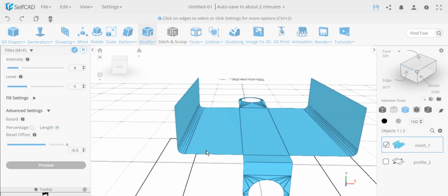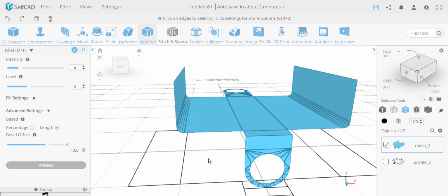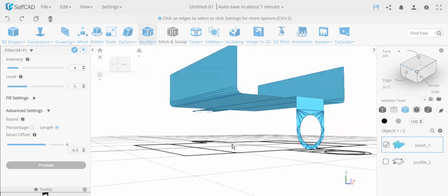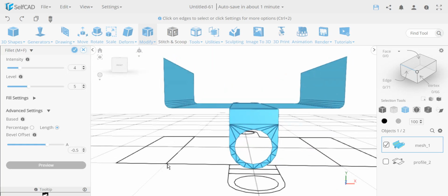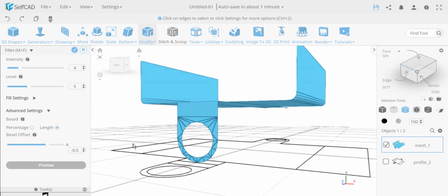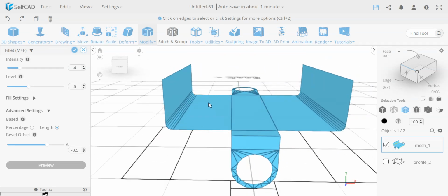Now this is the reason why I wanted to work first on surfaces instead of meshes. Once you have a mesh, the more complex it gets, you will have a lot more limitations. And if you have a mesh, you'll need to separately round the outside of the mesh, separately the inside of the mesh. But if I'm dealing with a simple surface, look how nicely this comes out, and over here I have no limitations, nothing, because we remove these extra lines, and this is actually very nicely done.